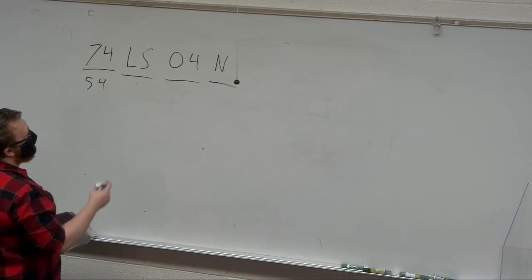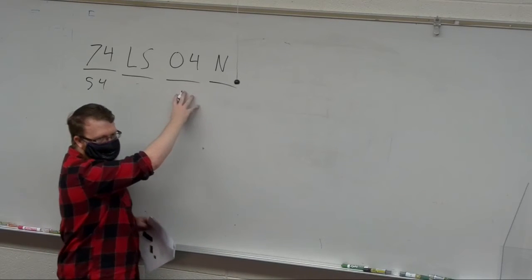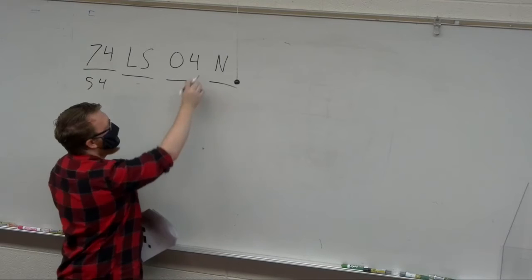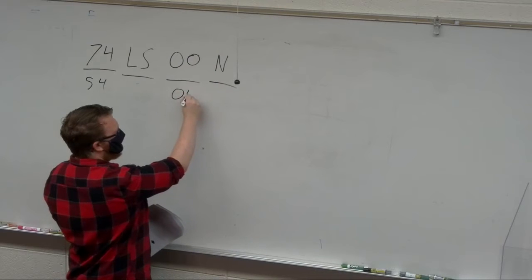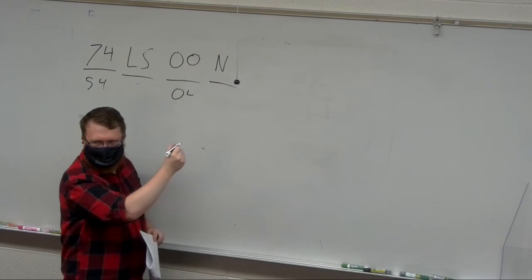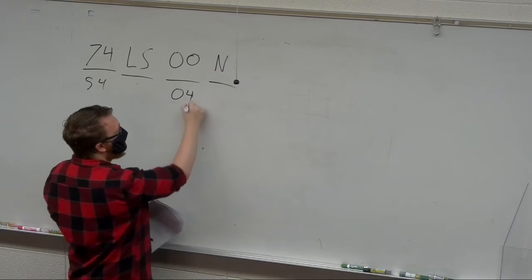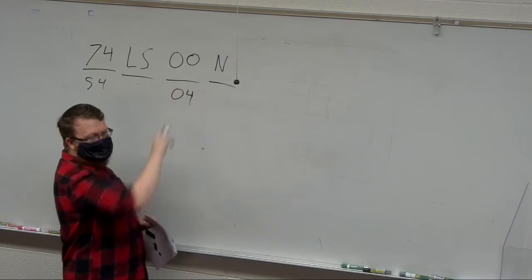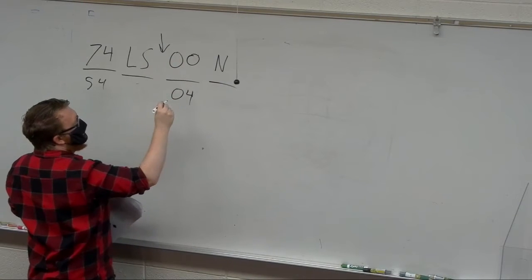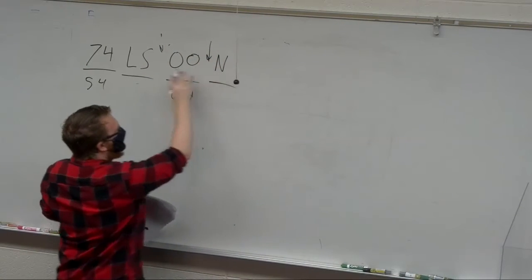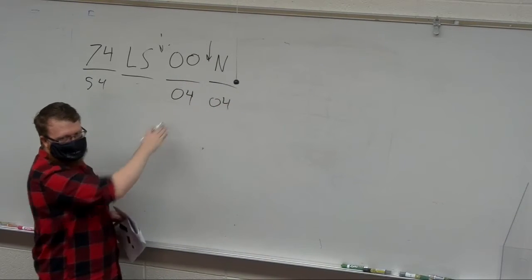So there's a couple different ways. The ones we're using, this isn't just a count of the devices. They're actually using this as the device type. So your 00s are inverters, right? Your 0, what did we use last time? 04 was the inverter. Oh, 04 is inverters and 00 is NAND? Yeah. Okay. Sometimes you'll see another term in here. Sorry, it would actually go here. So it'd be like 0004 or 0404 to say that you have 4 of this type of thing.